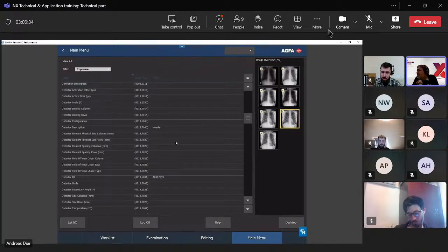In fact, each single needle has its own sensitivity, and this means for a needle IP we need a calibration file which is generated in production. This calibration file needs to be imported in the system, so that when you scan a needle IP, the calibration data will be applied to the image to have a proper image.